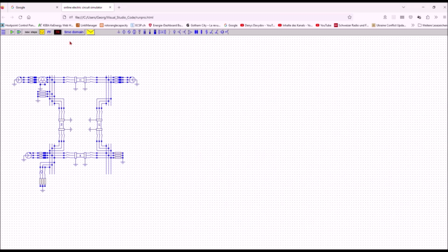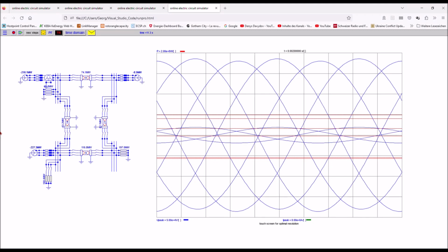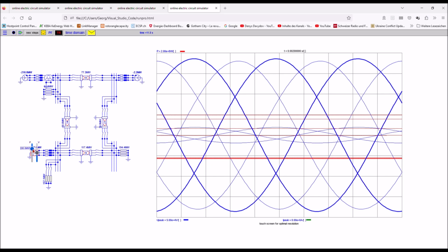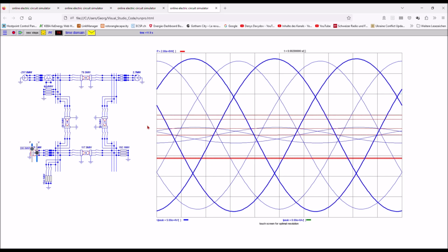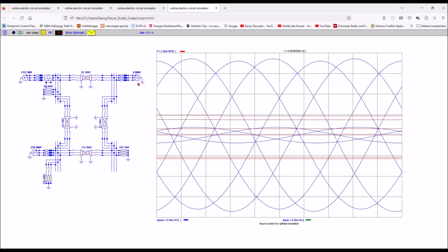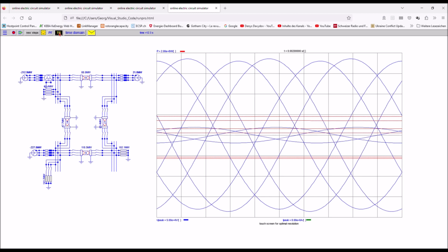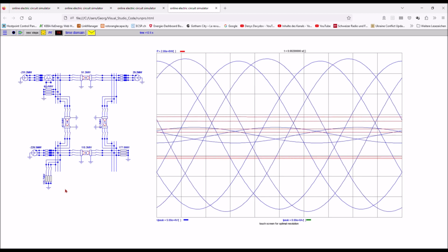If the recording is activated, you can also see the recorded traces by simply stopping the simulation. I can as well start recording after I prepare the conditions of the network. Here, before load rejection, the infinite bus to the top right does not contribute to the power needed in the network. Now, everything is okay. I activate the transient recorder. I reject the load.